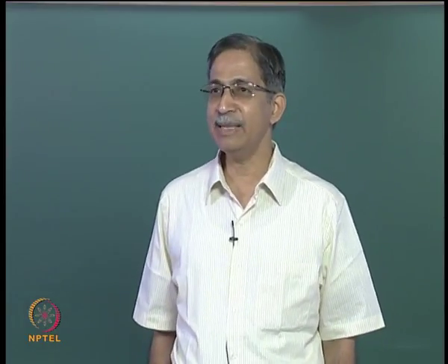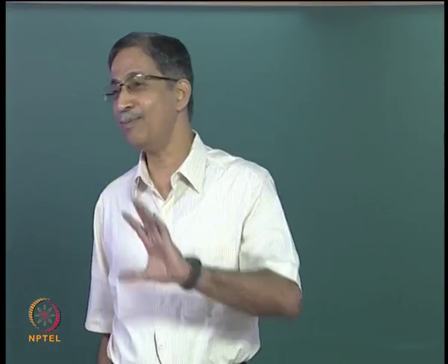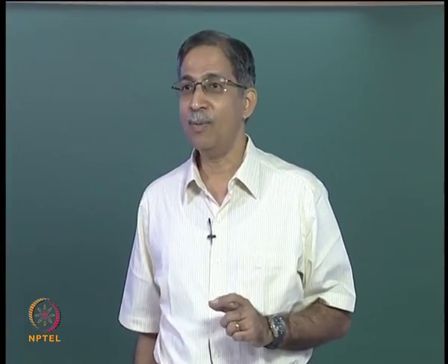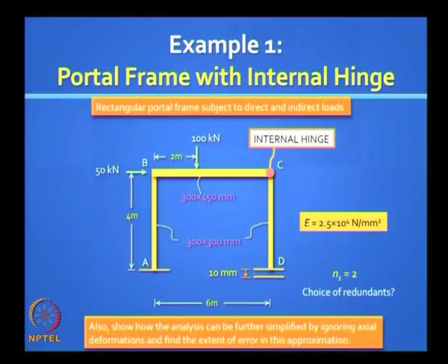What's the degree of static indeterminacy? Here we've put in 2 complications, okay, just to see how to apply this method. One is you have a support settlement, the other is you have an internal hinge. Okay, so if you did not have that hinge, you know that the degree of static indeterminacy is 3. That hinge brings your moment release, so it drops to 2. Now you can choose your 2 redundants.